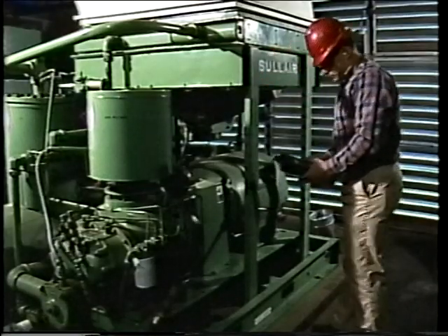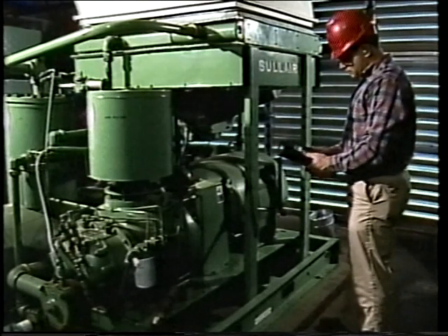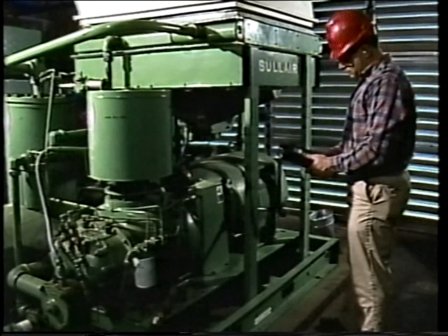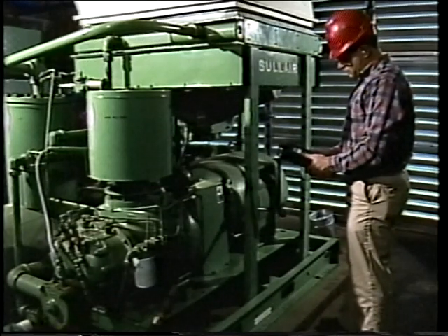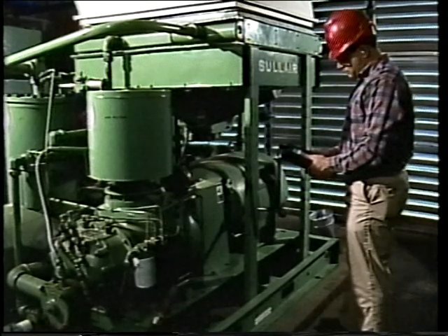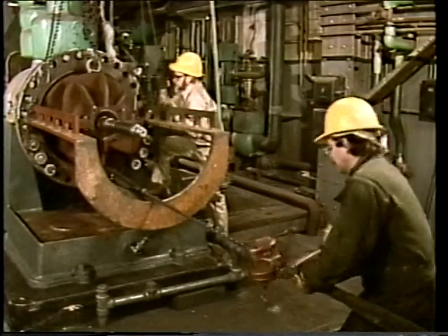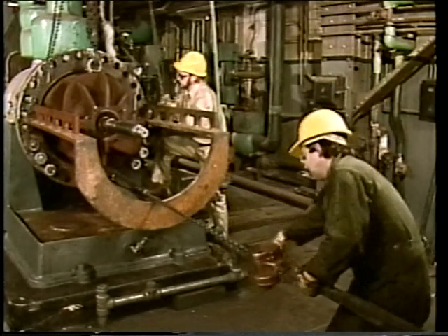Baseline data should be collected in a number of situations. For example, it should be collected when new machinery is installed, when a vibration monitoring program is started, regardless of the age or general condition of the equipment involved, and before and after any major maintenance or repair on machines covered by a monitoring program. Baseline data taken before repairs can be compared with subsequent readings to determine if the repair affected the vibration. The information will also serve as the new baseline for future readings and comparisons.